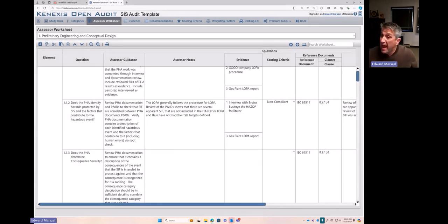But then after that, you generate your report, which is going to have recommendations. Put them into your recommendation engine to make sure that they are complied with and followed up with before you start your plant. And if your plant is already started, use that as soon as reasonably practicable rule for when you clear out those recommendations. So with that, that is functional safety assessment, overview of what it is, what you need to do.